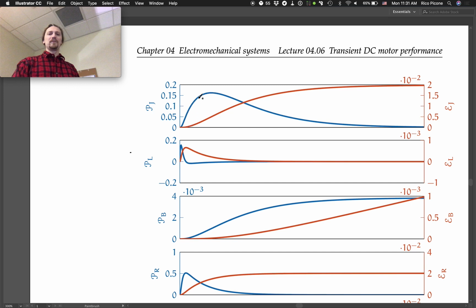So we speed it up, we flow power in, and then as we remember, it stops speeding up as we go. We saw how the speed of the flywheel approaches a steady state. So the power that we flow in is less and less. The torque that we're applying to it is dropping, and eventually that drops to essentially zero torque. The result is that we have this energy increase. We're just integrating the blue line here to get energy in orange. It accumulates, and we store some energy in the flywheel. We're flowing it from the electrical side to the mechanical side, and storing it in the flywheel.